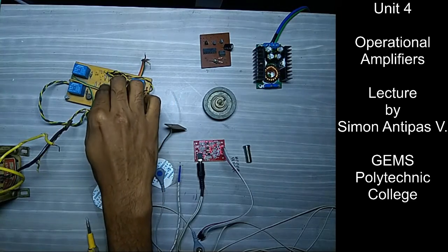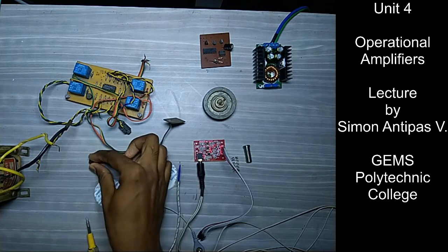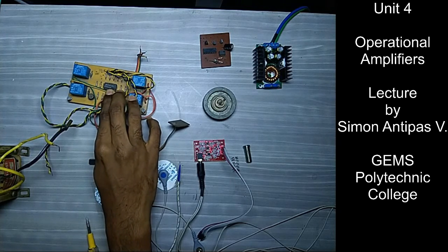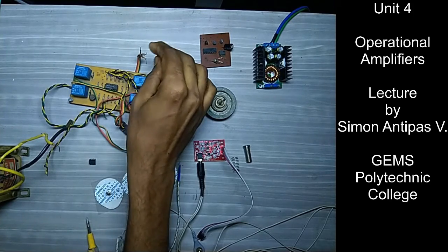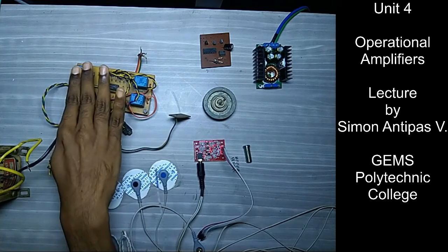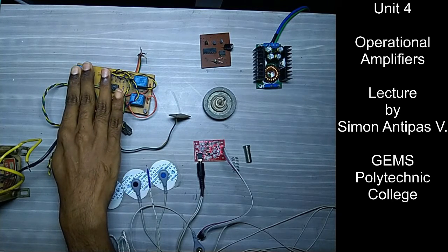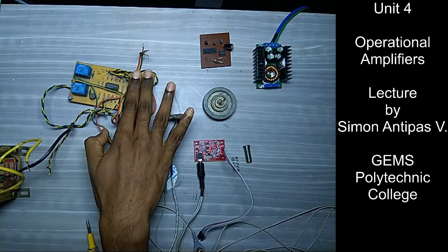That small input is given to an op amp. Now in this case, I have 4 op amps in one small package. As I talked about the resistance of water, I'm using that to measure this. So I have 2 op amps, 2 inputs to measure the tank water level, upper level and lower level. I have 2 inputs to measure the upper level and lower level of a sump.